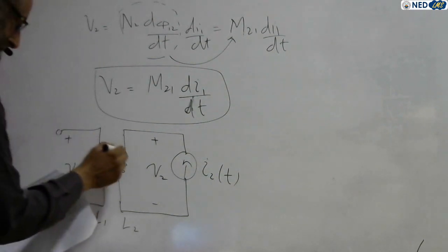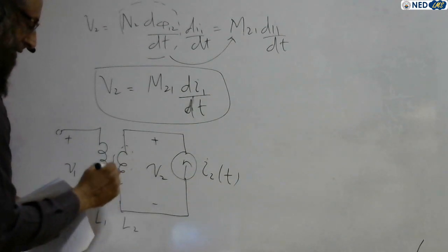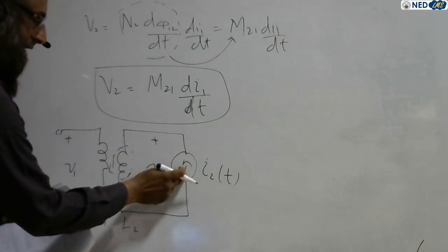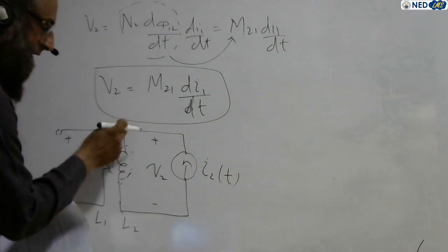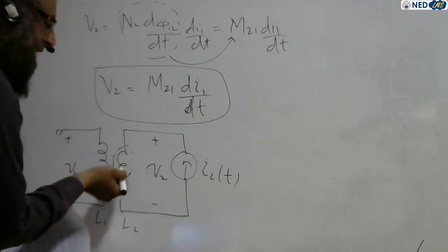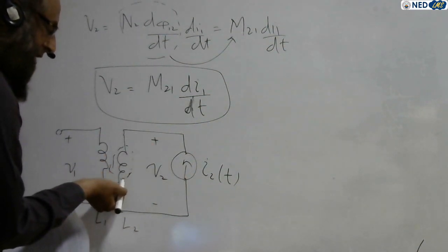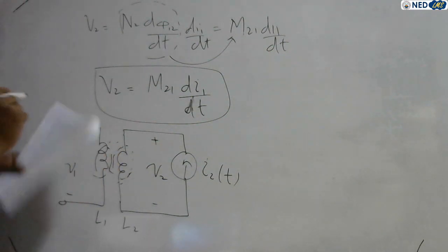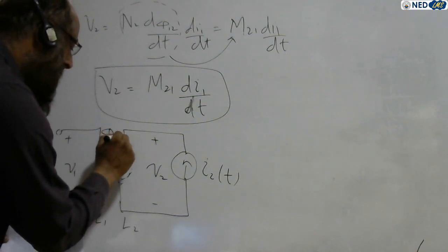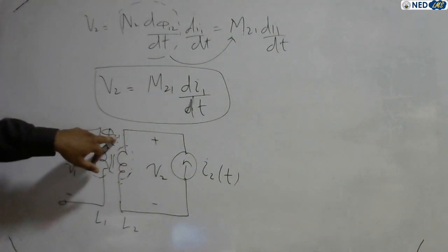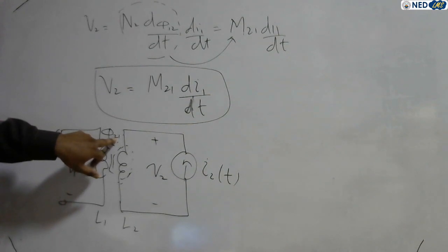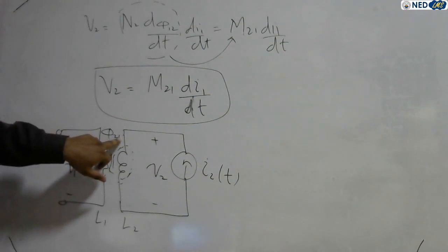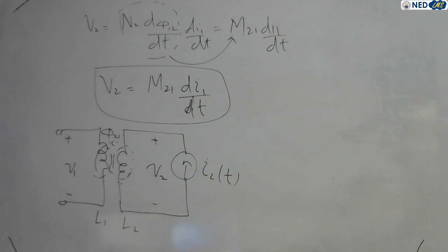So this time there are two flux, self-induced flux, that is change in current in primary coil induces a voltage in the coil, and change in current in this coil, that is coil 2, induces a voltage in the primary coil. So that one is this mutual, this phi 2 1, so subscript 2 1, that is change of current in secondary coil induced a voltage in primary coil. It is opposite. Before it was phi 1 2, now it is phi 2 1.